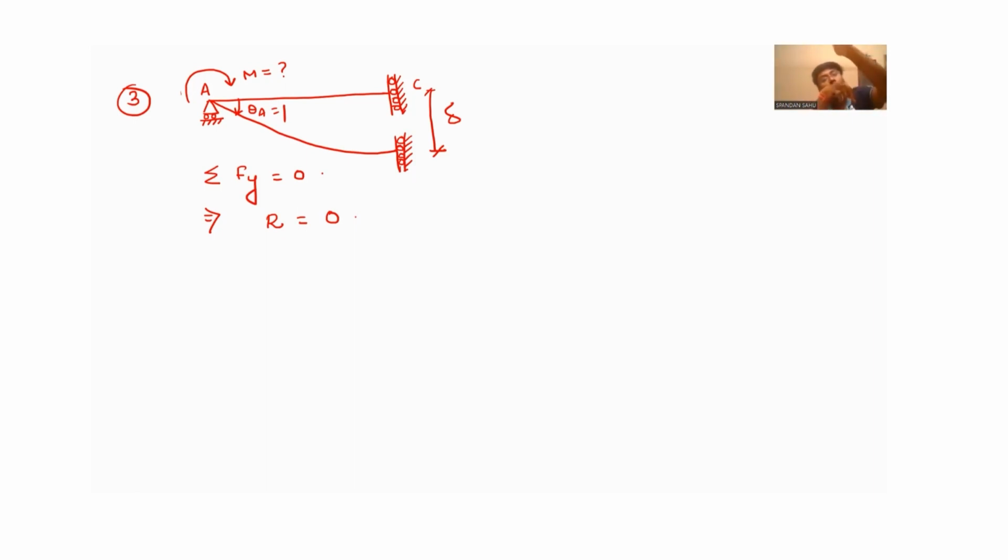So you are applying a moment M at joint A. Due to that moment alone, is your structure in static equilibrium or not? No. Then what should be added, or how will the reaction come, such that your structure will come into static equilibrium? We need to restrain the structure for unit rotation. Yes, sir. Now, is the structure in static equilibrium? Yes, sir.